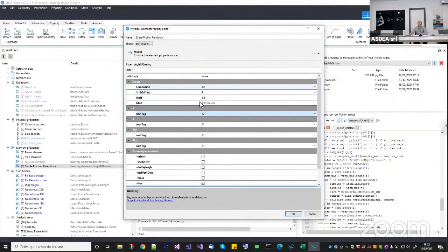Okay, then once you define the friction model, this friction model will act for the shear components. Okay, so in X and Y. But you still need to define something for the other degrees of freedom. So for example, P is for the axial force in the Z direction. And as I told you, I'm using the friction vertical, which is this one, the uniaxial elastic no tension.